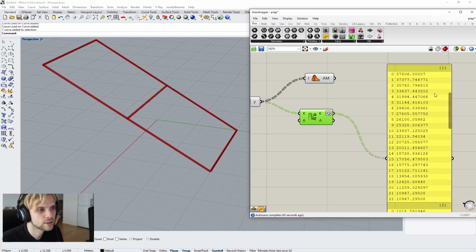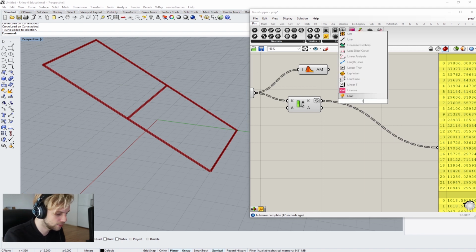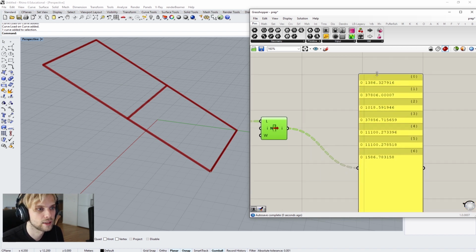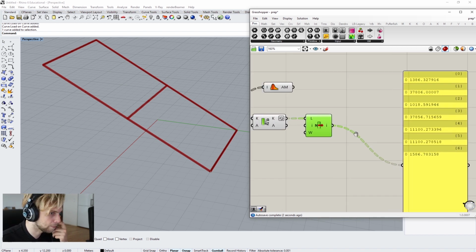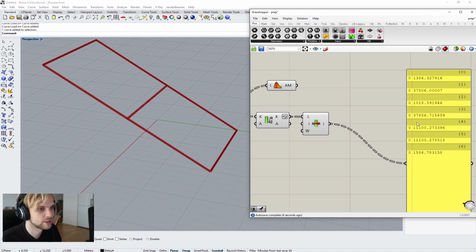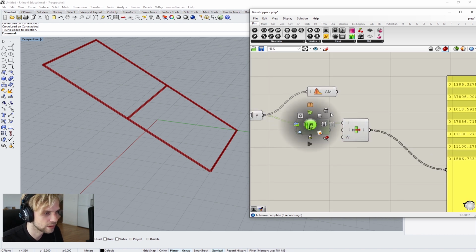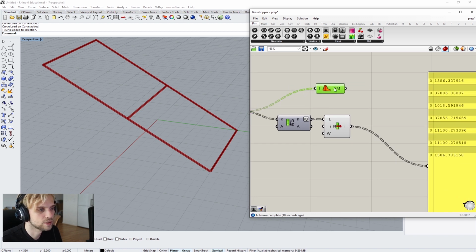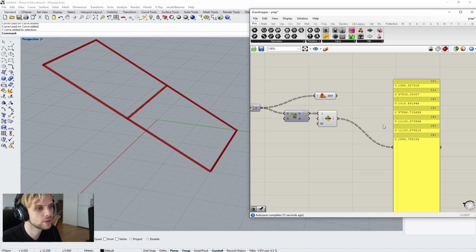All right, so here we have highest values always at the top, and all I need to do is just do list item, grab the first item of the list, bam. We have largest values, or largest stresses within each beam. Okay, so we have an average, we have the largest one.